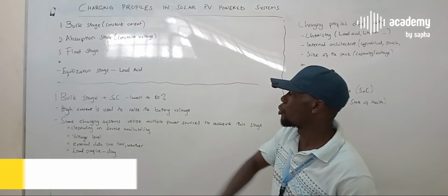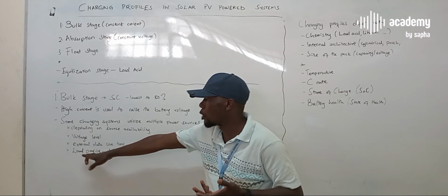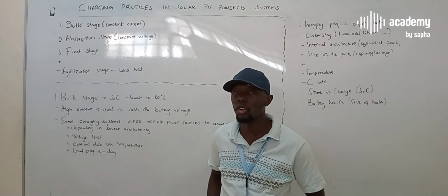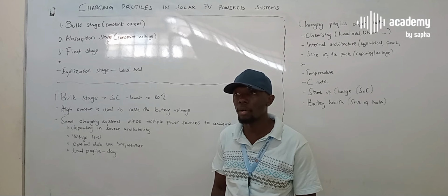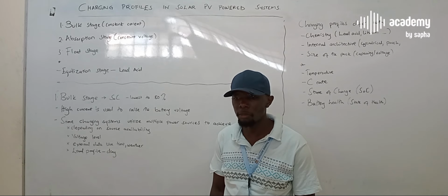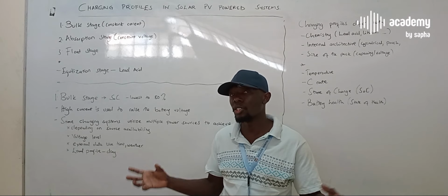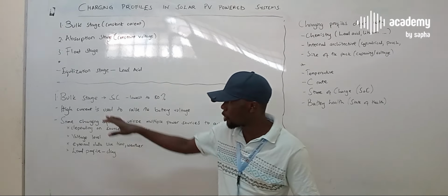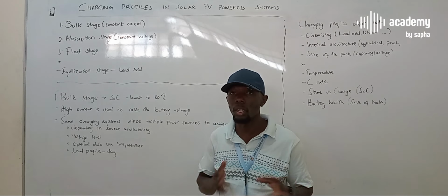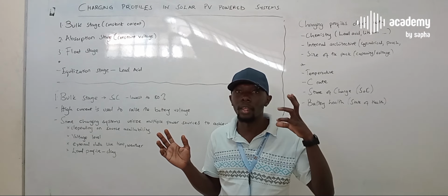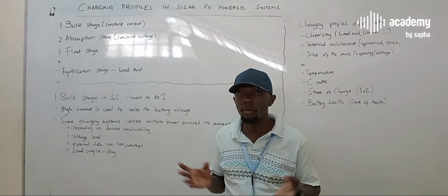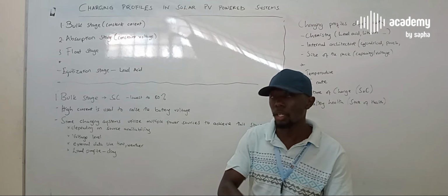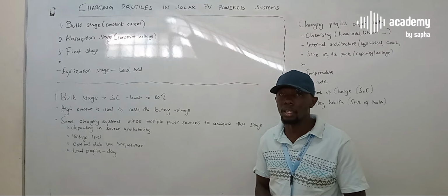And we've also said the load profile of the day. So some inverters will also listen to the load profile. If they realize that you've plugged in something that is normally not plugged in at that particular moment, they change the characteristics of how they do the charging or the discharging. And not even on the bulk stage, but in general, some inverters will listen to the load, the grid, the solar, all these parameters, and they make decisions based on that. But those are the way advanced inverters, not the basic inverters.